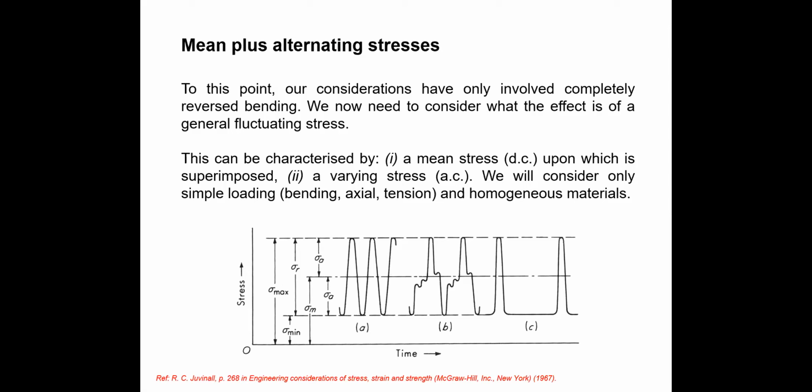If you remember, fully reversed bending means, I will draw it here. If we apply this kind of stress, this is called fully reversed. This is the positive value, assume this is plus 50, and this is minus 50. So it is a completely reversed compressive load. Consider this the tensile direction: if you apply the tensile load, within a few seconds the same point will be under compression. So this is fully reversed.